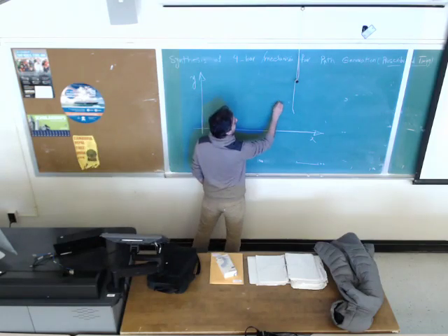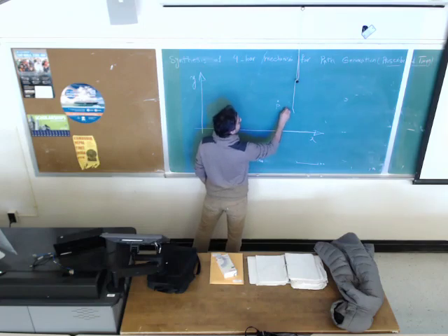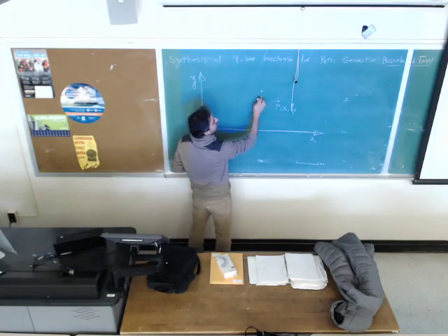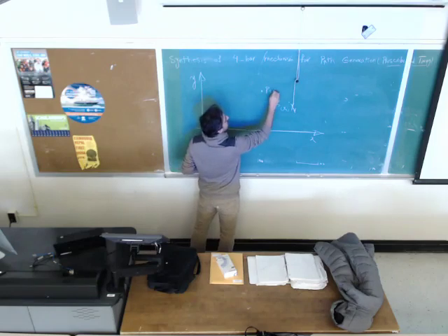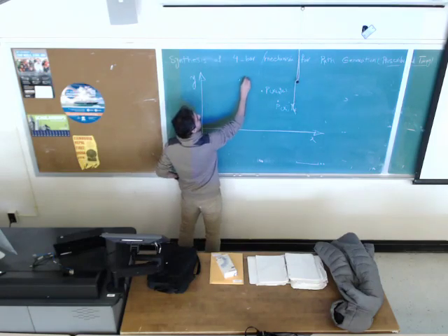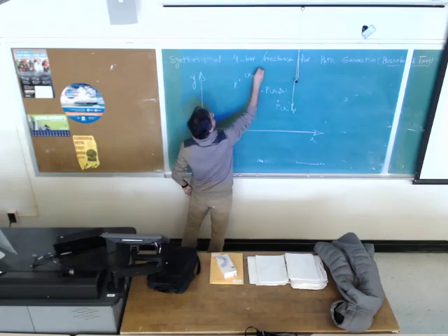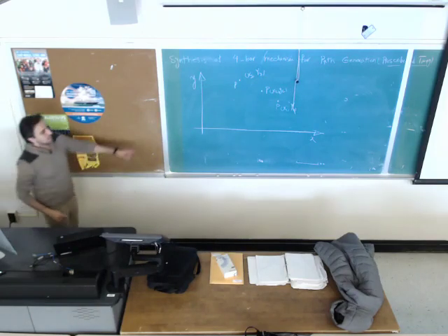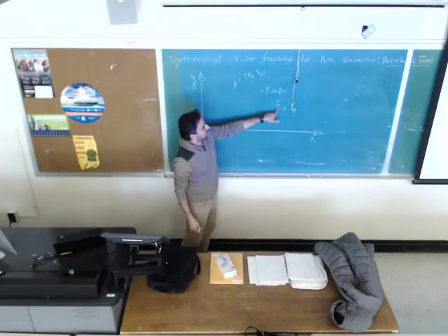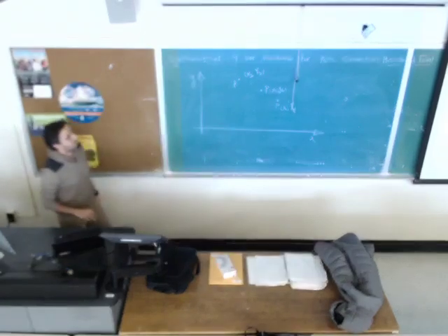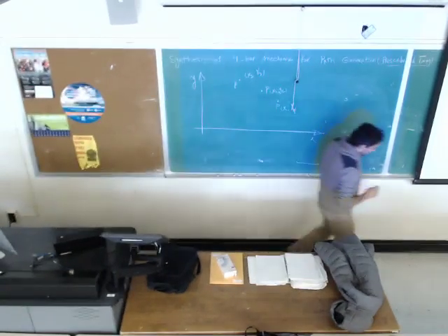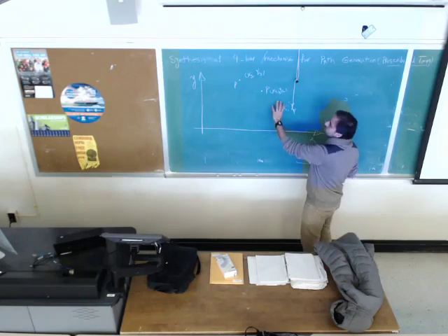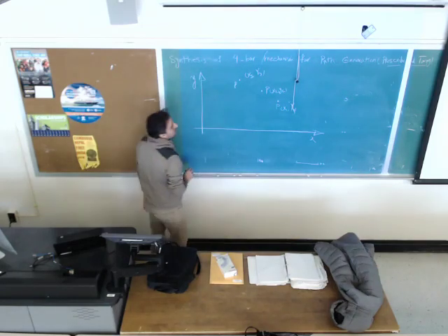So path generation: suppose point P is at coordinate x1, y1. You would like to move point P from this position to this position, x2, y2, and then x3, y3. So we are given three precision points: point P at the first precision point, point P at the second precision point, and point P at its third desired location. And you would like to come up with the design of a four-bar mechanism that moves point P through these three precision points.